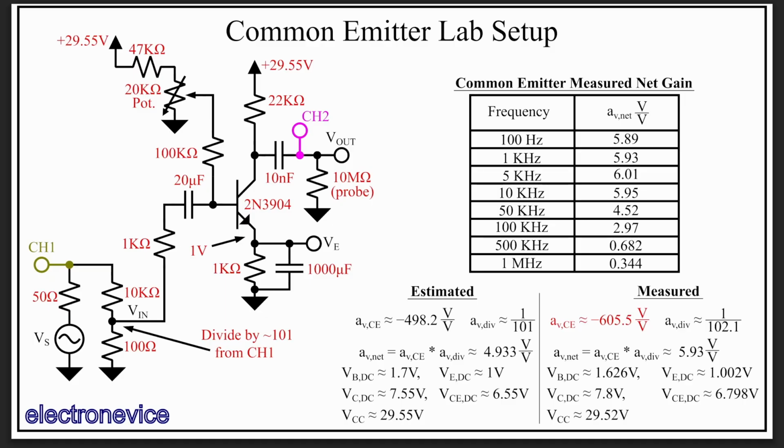So looking at the gain, we see that it rises slightly as frequency increases. This is likely due to one or more of my large capacitors actually being electrolytic capacitors, resulting in a relatively high equivalent series resistance, even at high frequencies. That high ESR is being bypassed by much lower ESR ceramic capacitors in parallel, thus leading to better performance in the mid-frequency range. However, as expected, the gain starts to attenuate around 50 kHz and becomes very small once we get to 500 kHz. We'll look a little more closely at these results once we've run the same tests on the Cascode and can compare them.